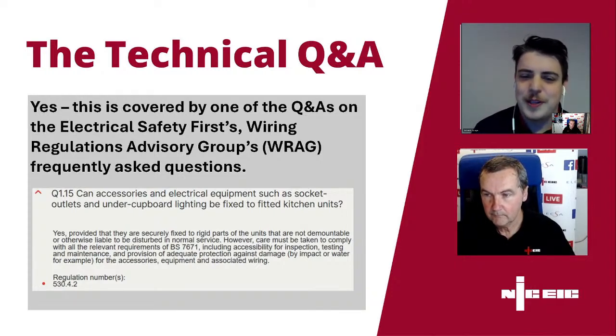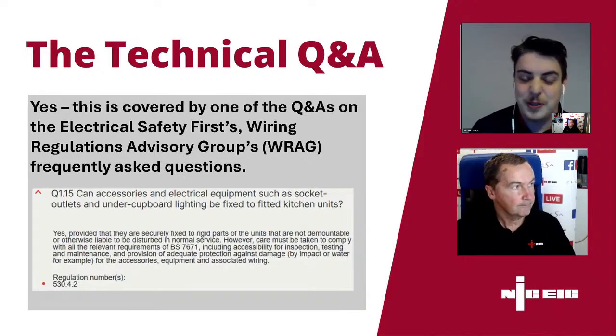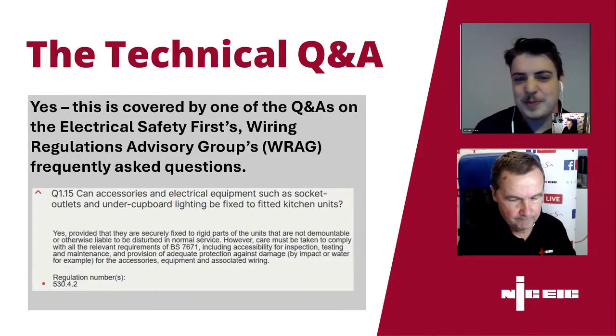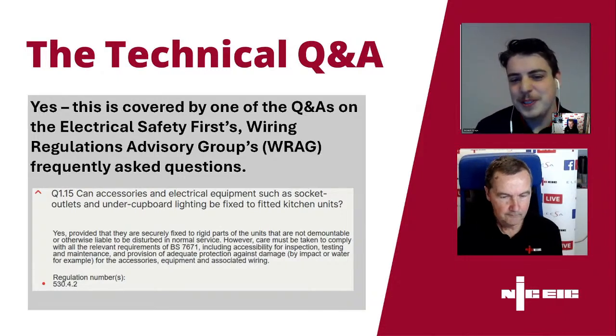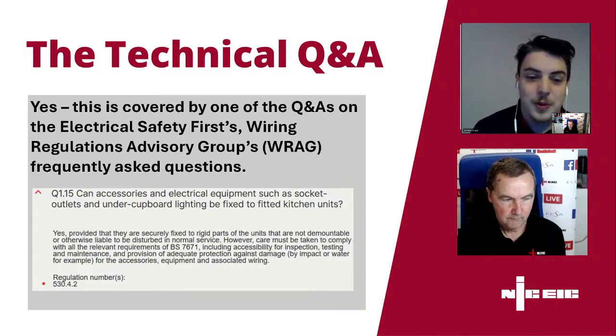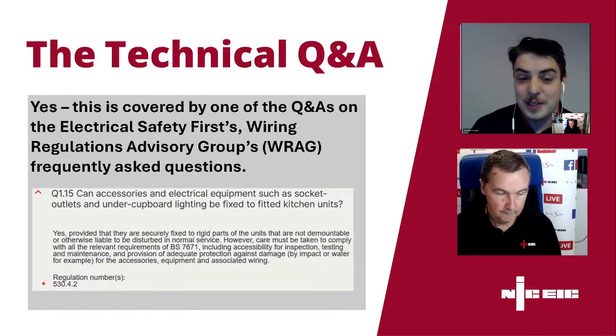Also avoid any places where there's water. Try not to keep it too close to them at least, so it's well out of the way, if it's under a sink, say. You try not to go there, but if you have to, just make sure you're keeping your distance. And you might have water heaters under the sink or boiling water taps and everything. You want to make sure the wiring system's protected from any adverse effects from heat, water and the usual requirements really, but it's acceptable.